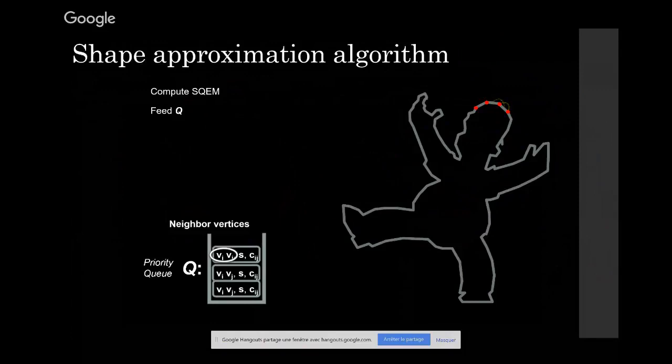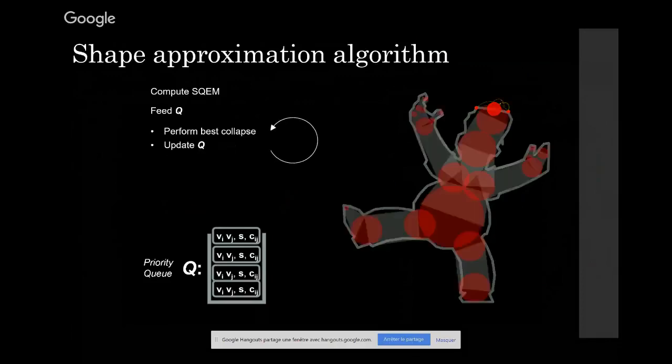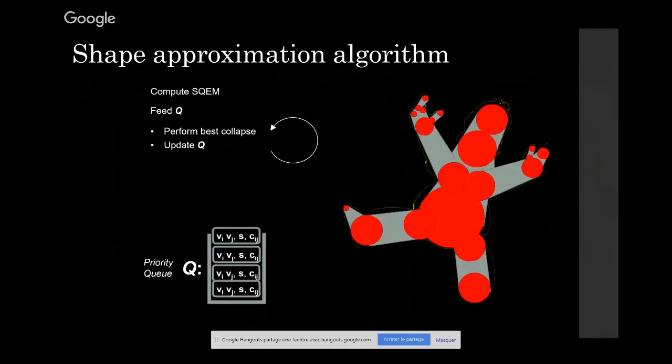You collapse it, and basically you replace it by the optimal sphere defined by our optimization for this particular edge. Remove the edge, collapse, reinsert the approximating sphere, and iterate. So you're going to basically reinsert the new edges which have been created. This is a priority queue, so all the elements stay ordered based on the cost defined by our quadratic. And we do that for a bunch of edges until we reach the resolution we want.